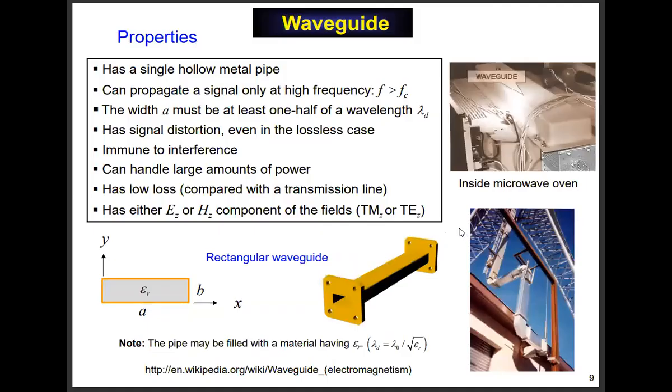Okay. All right. Now, finally, waveguides. Remember, the word waveguide means hollow pipe of metal being used to transmit an electromagnetic wave. It may seem kind of surprising that a hollow pipe of metal can be used to do that. A transmission line requires 2 conductors, right? But that's a TEM mode. But a hollow pipe can also be used to transmit an electromagnetic signal, and that's, again, the entire subject of notes 20.